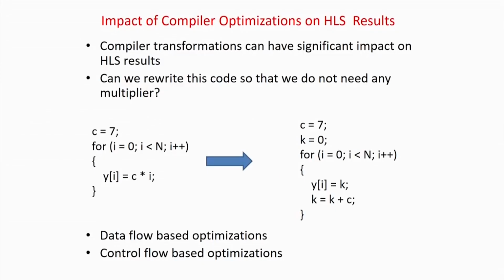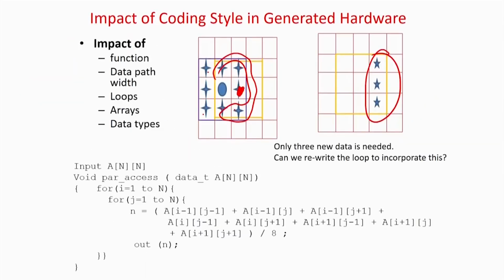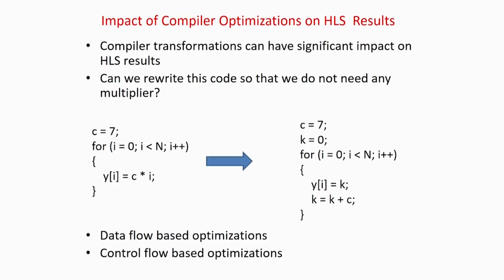So the first level will be design optimization at the high level, the specification level or the abstract level: how good quality code can be written so that you can have a good quality solution at the end. Whenever you are writing high level code in C language, there will be a lot of compilers involved, which will generate the Verilog code, because you have to finally get the RTL design. That part, as I told you, is more or less automated. We will write some C code like this, or something simple like this. Finally you are going to get the gate level implementation by automatic tools.